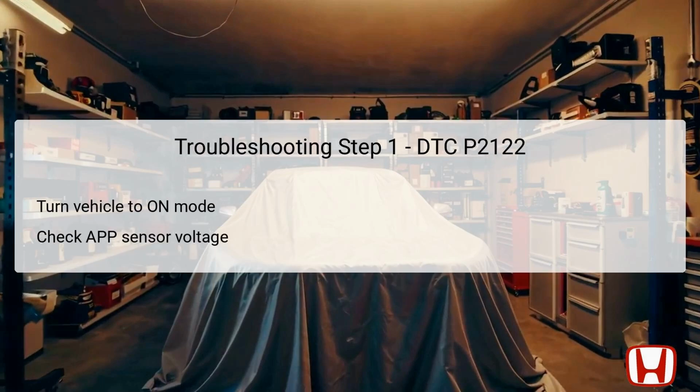To initiate troubleshooting for DTC P2122, first, turn the vehicle's ignition to the on position, ensuring that all electrical systems are live without starting the engine. This step is crucial, as it allows the handheld diagnostic scanner, known as HDS, to check the APP sensor A voltage. According to the diagnostic manual, readings below 0.2 volts signify a fault condition that necessitates further inspection.